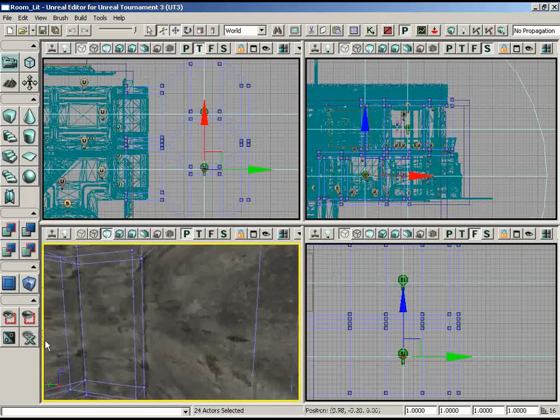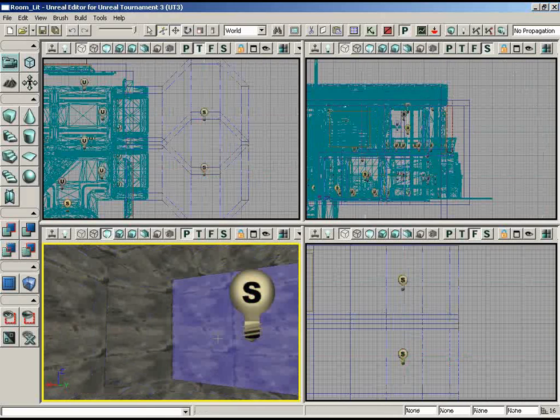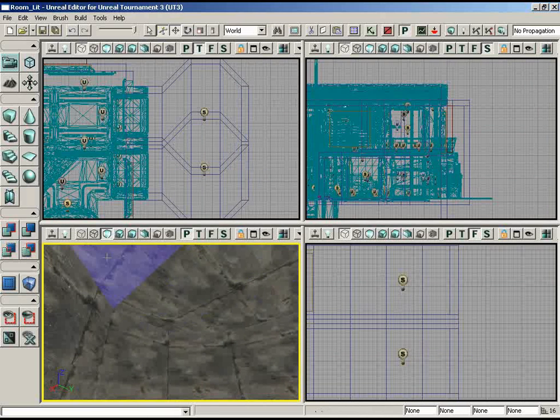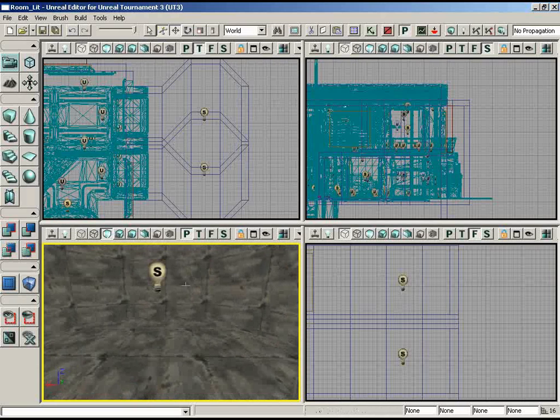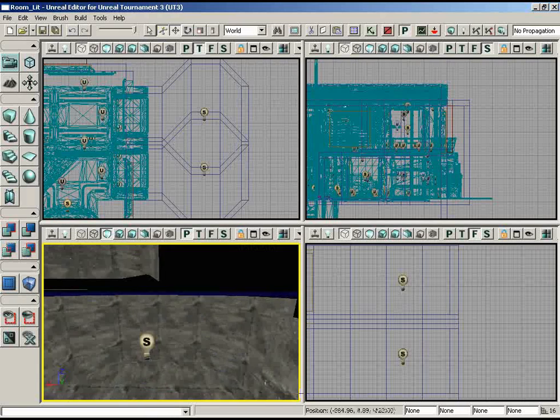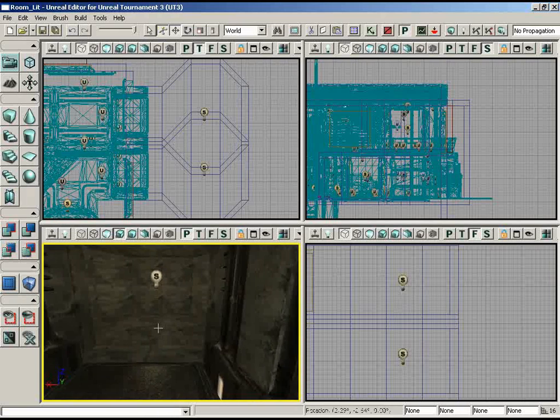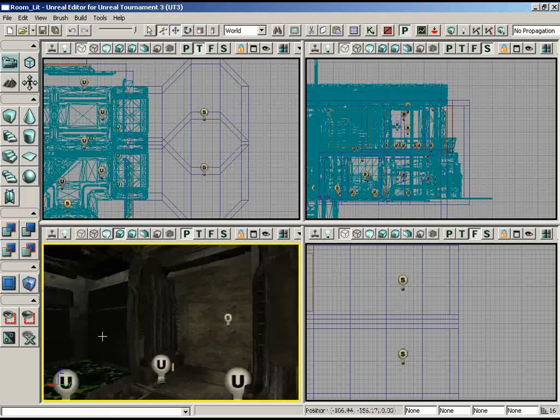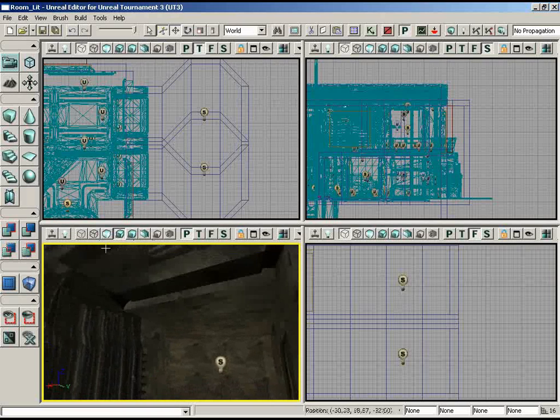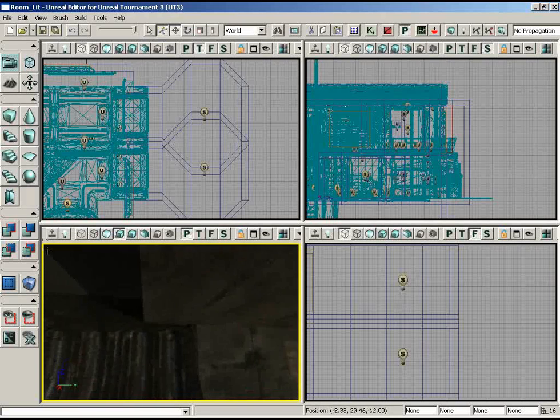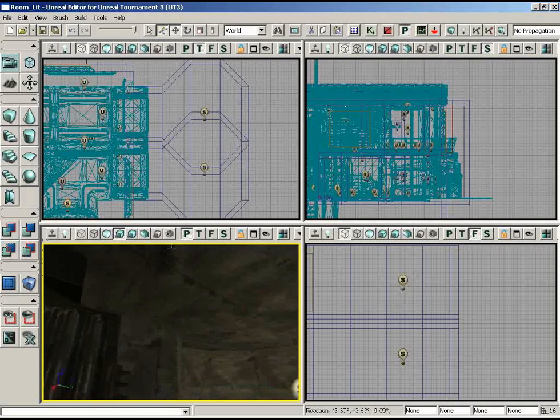And that's looking good. Now on the bottom, we deselect everything we have, the ceiling, and none of the ceilings are overlapping. We don't even have any texture problems. Cool. And if we turn lighting back on, we could build lighting, but we're not looking for anything too impressive in there. Right. The ceiling on this side, you can kind of see the ceiling through the mesh though.